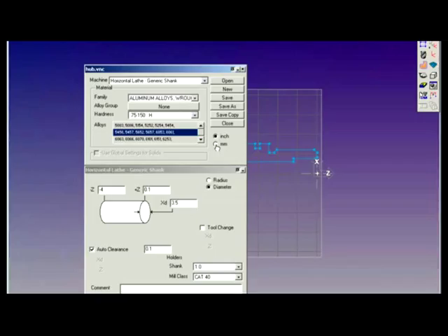It is not advised to change units in the middle of a part. If, in fact, you are working with a part that is defined in inch units, it is not a good idea to change to millimeters in the middle of the part. What this does is it alters the size of the units and converts from inch to millimeter.